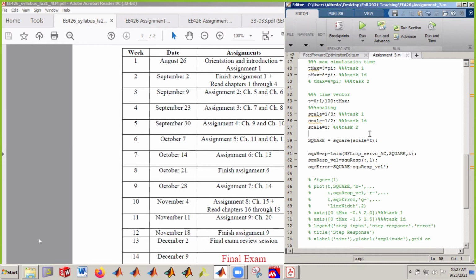For example, an airplane flies to very different dynamic pressures, to different altitudes. The pressure, the temperature, all these things have an effect on the system, so it behaves differently. So your control may not be able to tackle all these possible operating conditions. So you may want it to adapt itself so that it can self-adapt to the particular condition that you're trying to control.